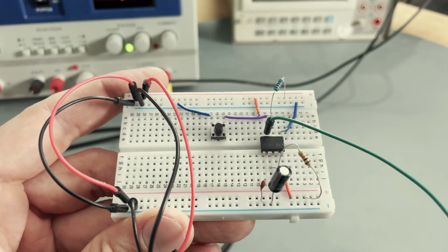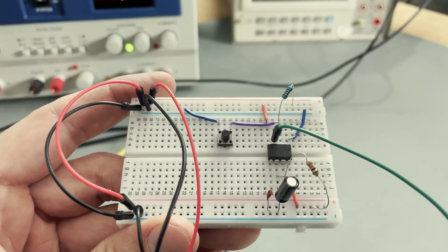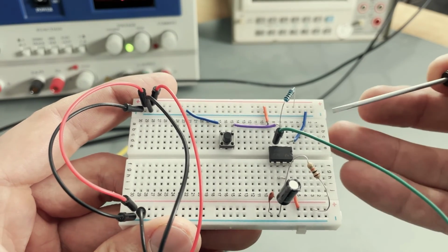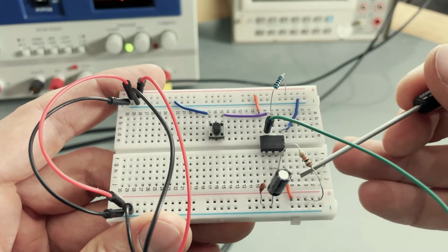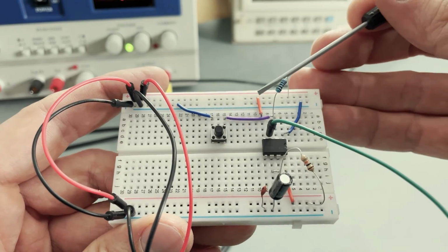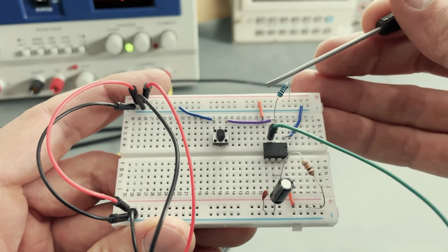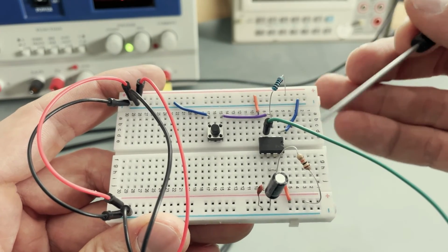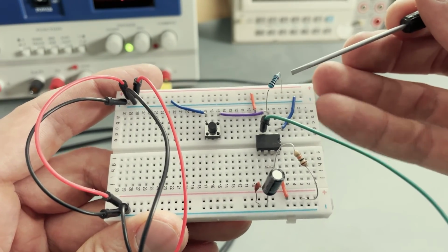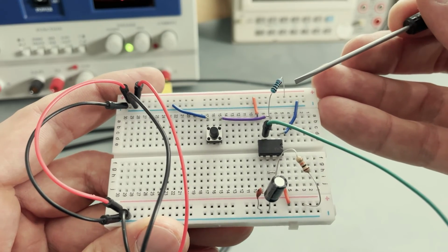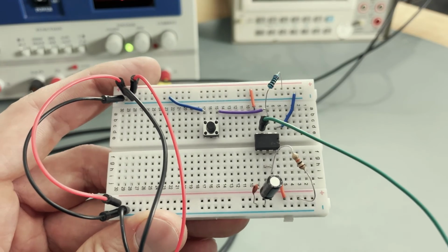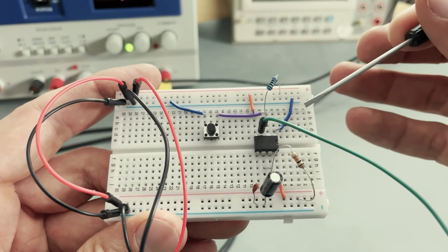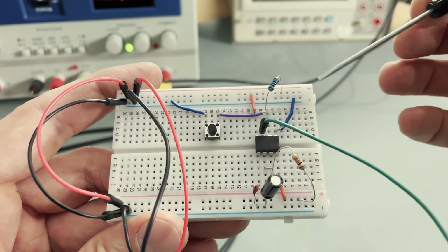Everything else is simply to connect it to the power supply and to the oscilloscope, and also just so you can provide ground and power. Pin 4 is also on power, which, if I don't remember off the top of my head, I think it's pin 4, the reset to the flip-flop. We just want to tie that to VCC so that we don't accidentally get a reset. So that is the actual physical circuit that we're working with. Let's get this trained on the oscilloscope and see it in action.